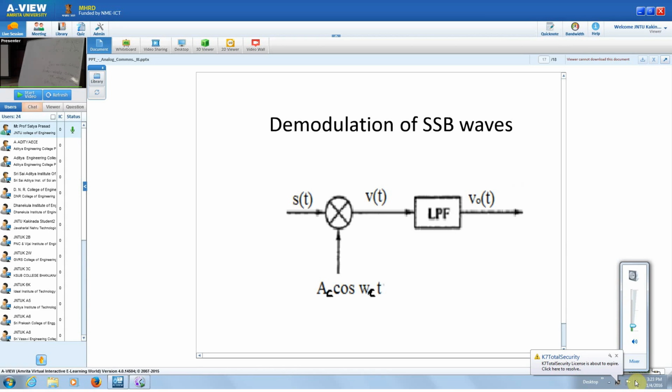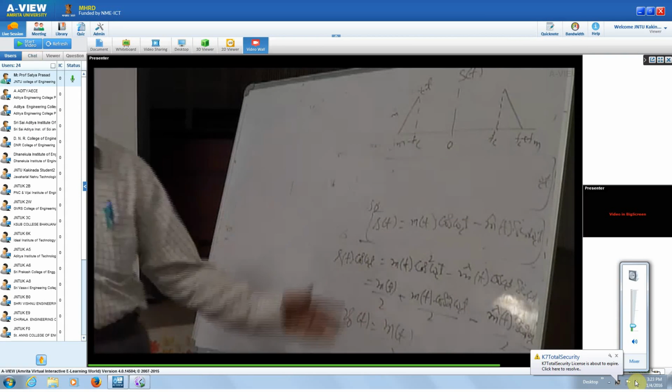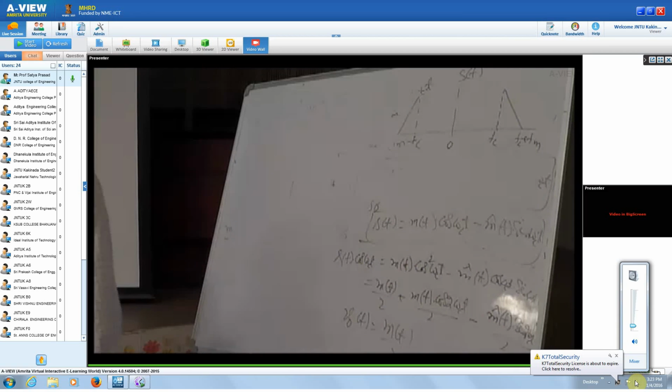In the modification, if a carrier is also transmitted along with a DSB SC signal or an SSB signal, that carrier we are going to transmit sometimes. So how are we going to achieve the demodulation without that coherent detection? The disadvantage that we are having so far is how to generate a coherent carrier, since any variations may be reflected in the recovered signal, whereas we'll sometimes be sending a pilot carrier.